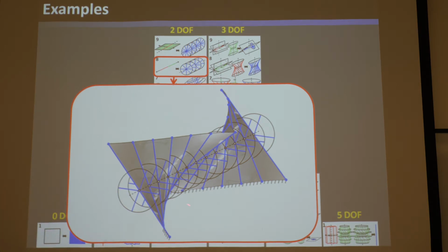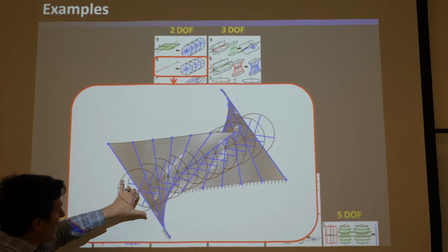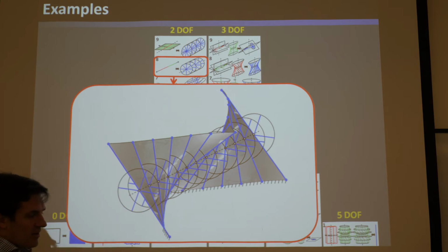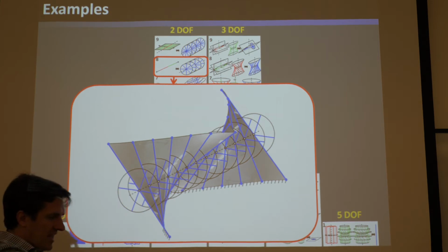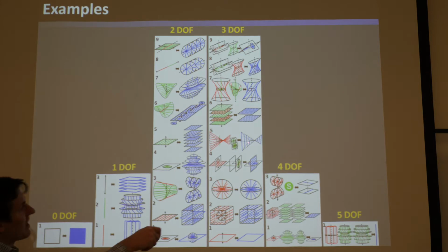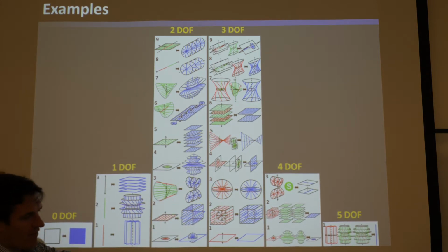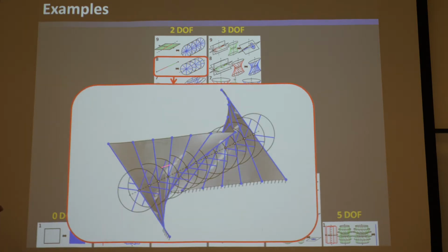Now, you have to be careful with this, because if I had generated this ruled surface of blue lines by translating and rotating with the same pitch, such that the double derivative with respect to the displacement is constant, then it would be a hyperbolic paraboloid, and it would lie within this one. Okay, so if you rotate those at a different rate than a hyperbolic paraboloid, you're going to get this one. Whether you go forward and then back like we did with this one, it's clearer and it's a more symmetric